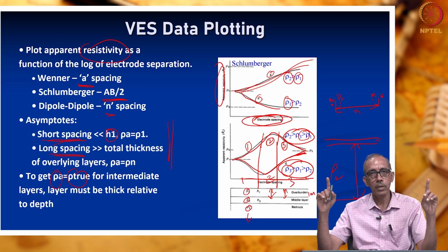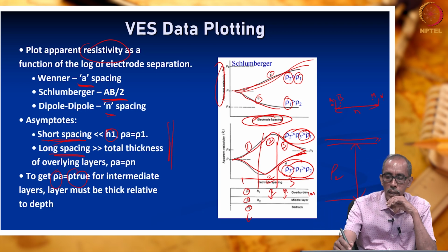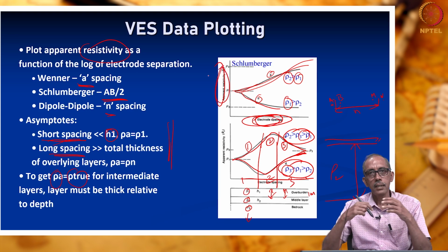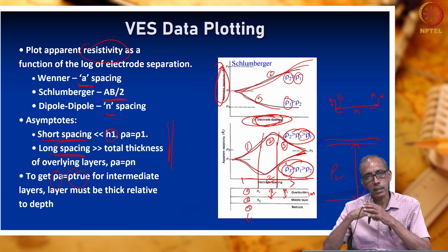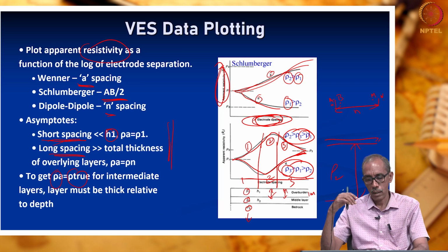This can be done by any method, though carrying out vertical electrical sounding by Schlumberger is a little bit easier. Interpretation is made by drawing a plot of electrode spacing versus apparent resistivity. In the next lecture, we will continue to explore how the interpretation of the resistivity curve is made by different methods. Thank you very much.